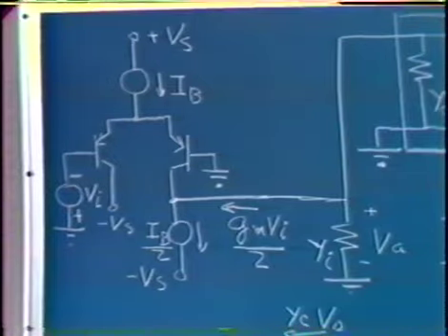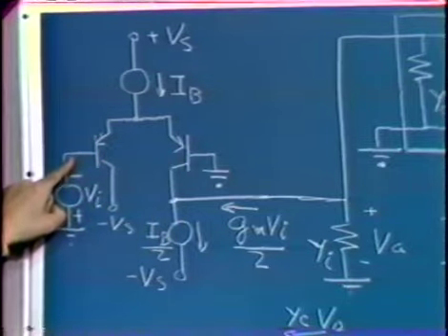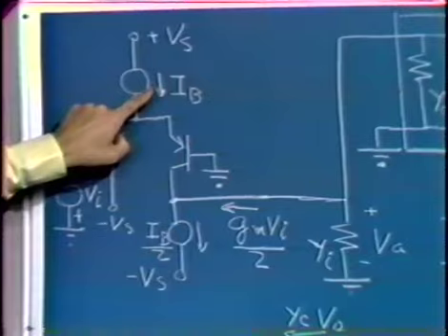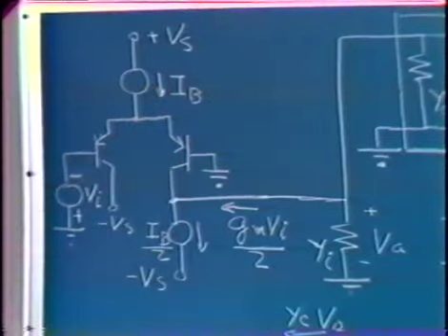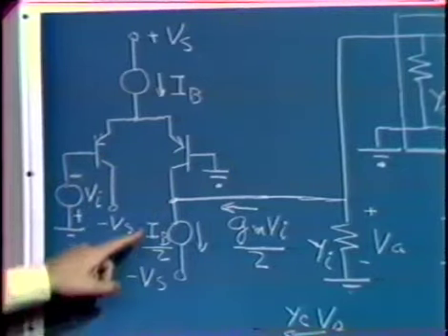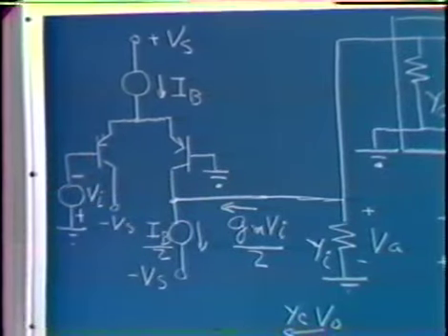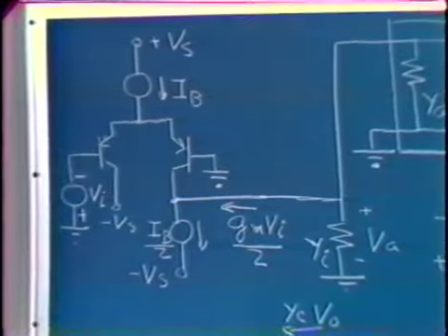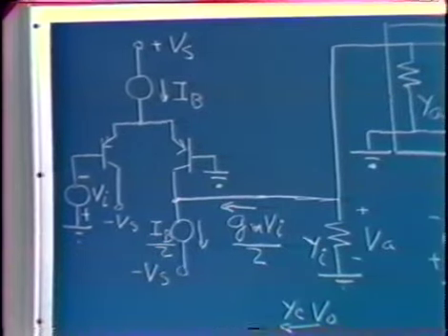The rationale for that, of course, being that if these transistors are well matched, when we had VI equal to 0, the current applied to the emitter of the differential pair would divide equally between the two members of the pair. Consequently, the quiescent collector current of this transistor, with 0 volts applied to the differential pair, would be 1/2 of the bias current.